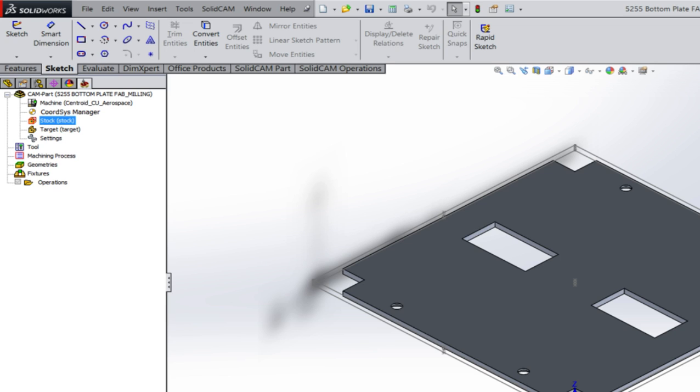Throw a tape measure or some calipers on there. If you cut it really wavy, try not to do that first of all. But if you did cut it really wavy, try and average out the wave when you measure. Try and get an average for that wave. Or if you want to be super safe, measure the thinnest portion of that wave and make that your stock. Okay?